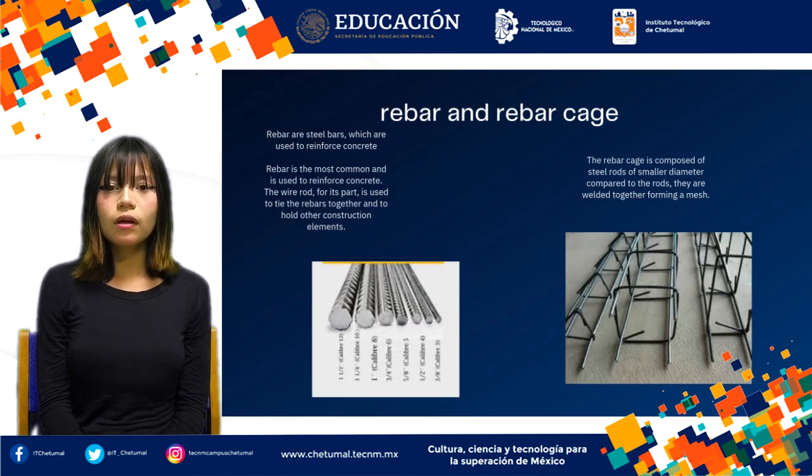We begin with the local stone foundation, a traditional option in areas where this material is abundant and cost effective. This type of foundation is mainly used in low rise buildings and stable soils. Characteristics of the local stone. It is a natural, irregular, and high strength stone. Placement is done manually, arranging the stones so that they fit well with each other, avoiding large gaps.